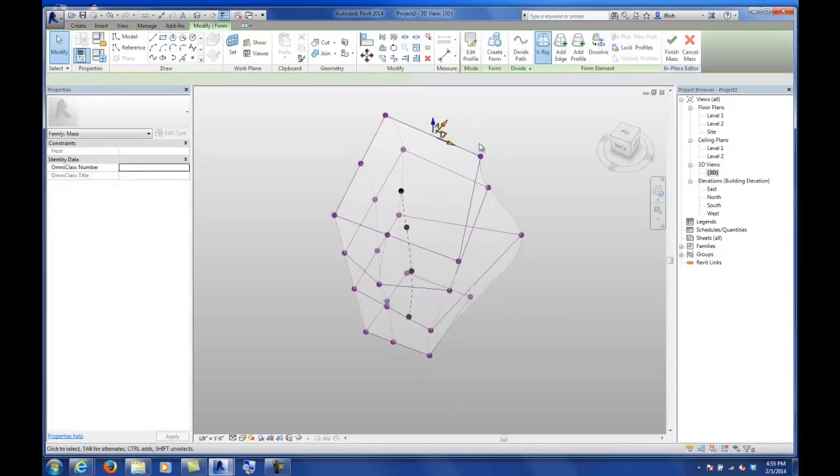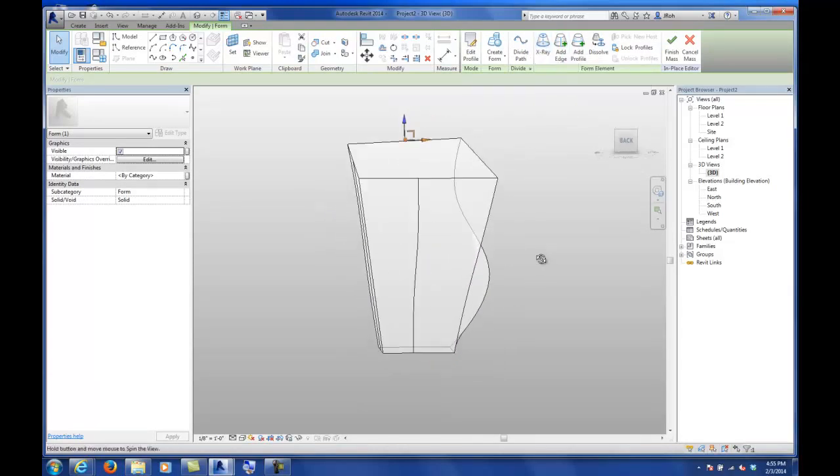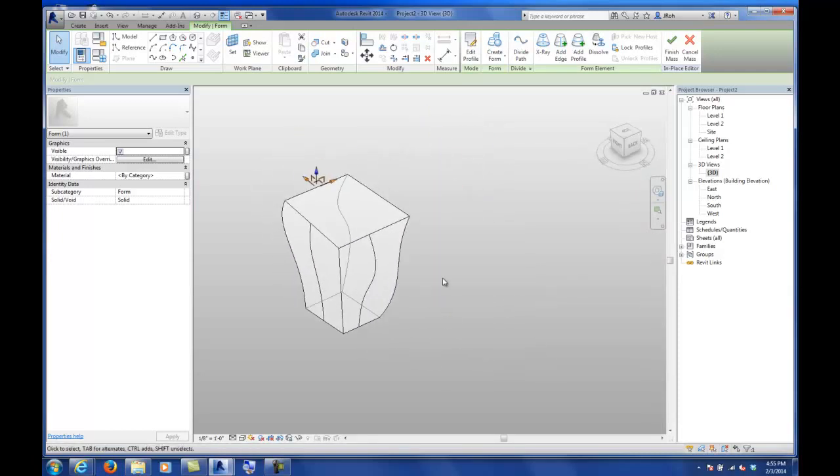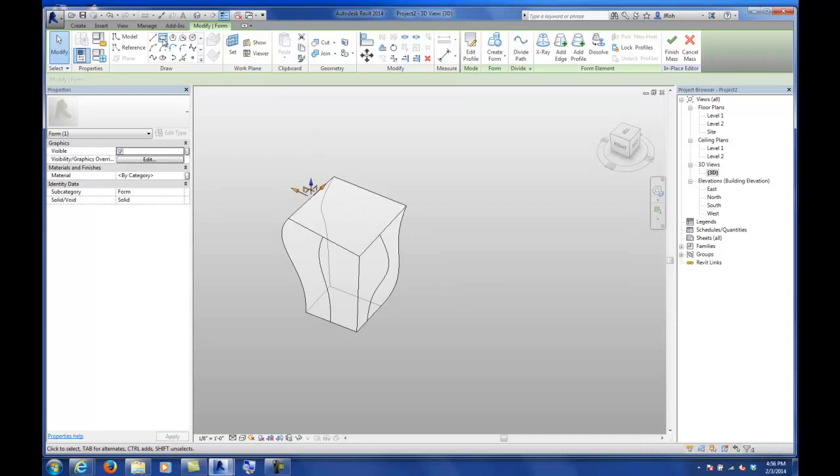Once you're out of that X-ray mode, I can click on that mass and just uncheck the X-ray, come back to that element, and we've got that particular component. Another thing we can do in this intuitive massing mode is think about a mass first, and then ways of pushing and pulling it to make solid geometry, but at the same time we can make void masses that can start to cut out, a kind of stereotomic way of working where we're slicing and carving out different parts and pieces of this particular mass. We can draw as many of these masses as we want.